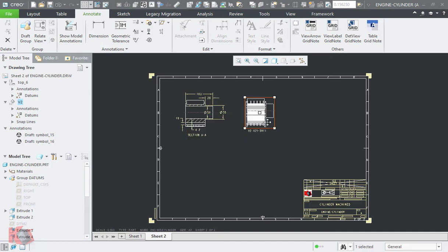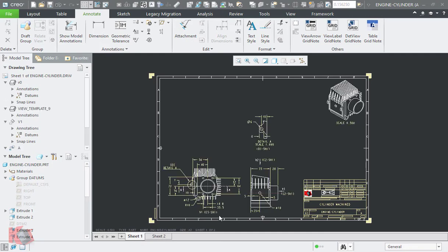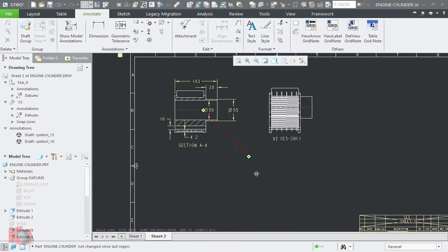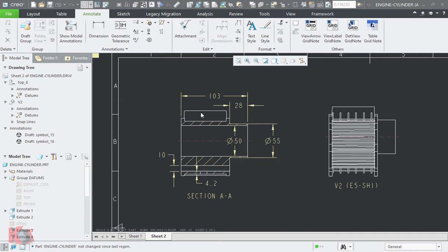Grid reference will update automatically in the notes if moved in the same sheet, or needs to be regenerated to update the notes. Once done, your drawing is ready for easy navigation across sheets. Thus the relationships between views by grid reference give you the most needful information to easily find the view of interest in the multiple sheets drawing.